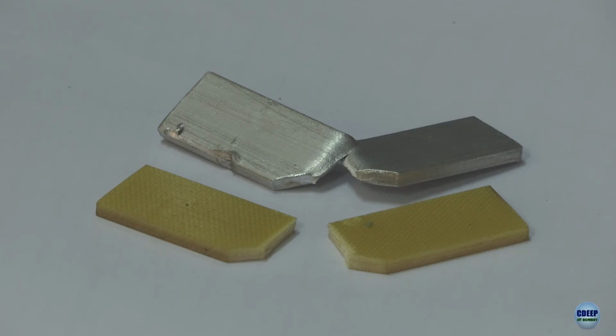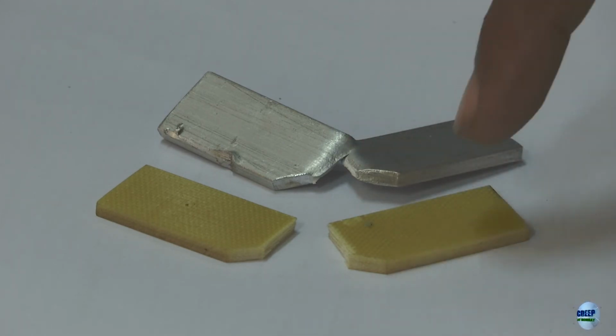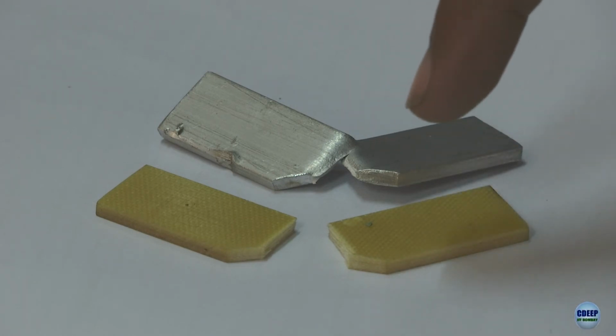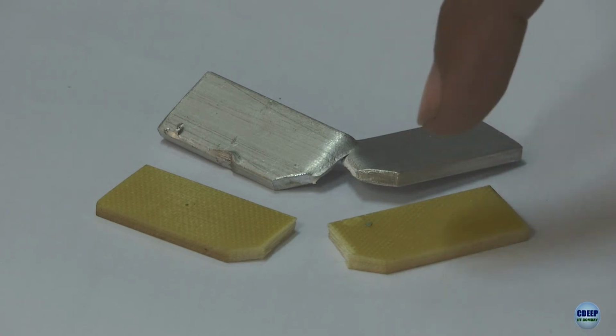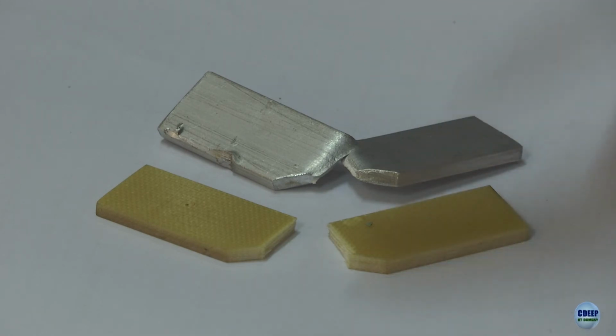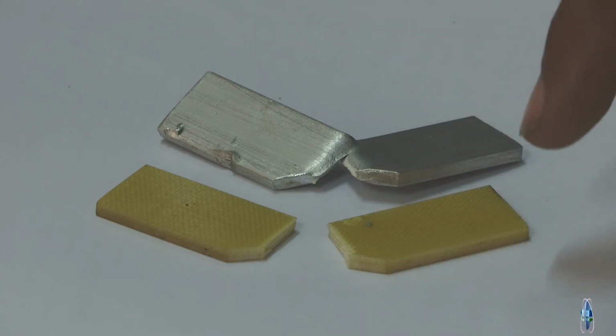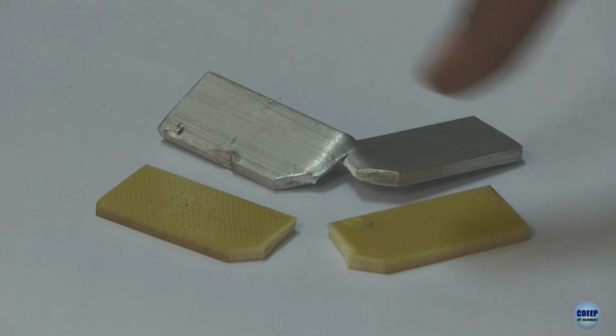Now the way to calculate is, we know the energy, we've seen it on the dial, divided by the area. That gives you the impact strength of each material, and we will provide you all with at least 10 specimens or more if possible, the data of them, and then you all have to actually calculate the impact strength and also see the variance of the materials. Now since fiberglass is a more involved process of manufacturing, you might see more variance in the results. So keep an eye out for that.